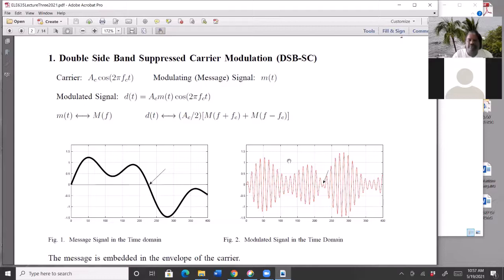You know how to rectify an AC signal and get a DC signal. And if you have a capacitor, then when it goes here at the peak, it will start to decay and it may not come to zero quickly. It may go somewhere here and meet the next peak a little bit below the peak.